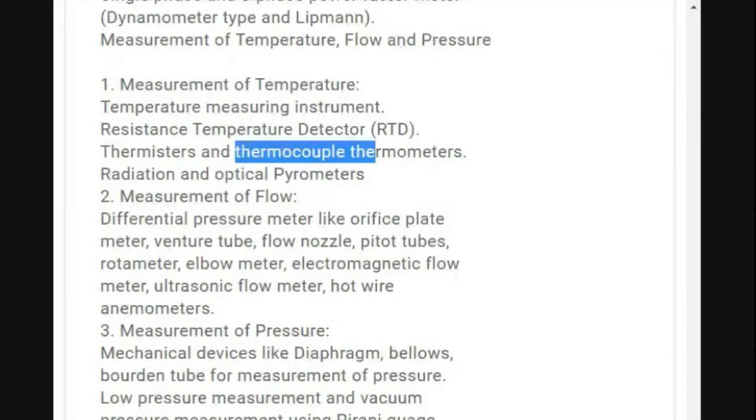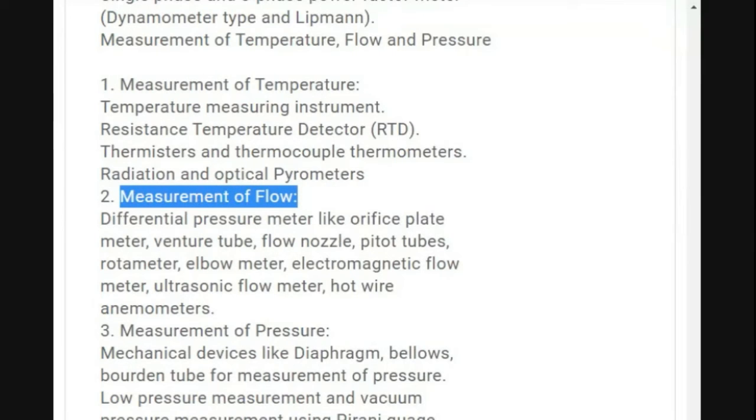After that, in the measurement of flow, we have a very basic technique called differential pressure measurement. Now what do you mean by that? If there is a flow, you can observe that without a difference in the pressure between the starting end and the receiving end, your flow will not happen. If this pressure difference is very high...